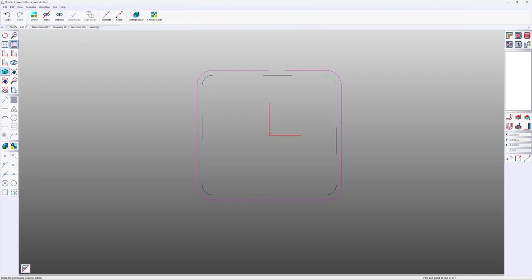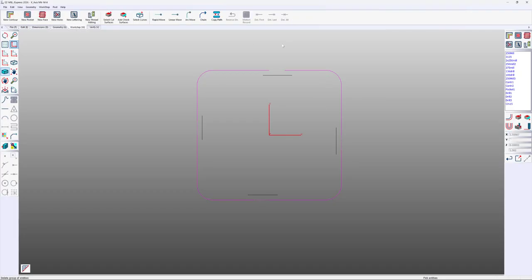Then I'll just go in and delete, just cleaning it up a little bit, get rid of the geometry I don't need. So remember that curve was still active. I didn't delete it, I just cleared the links. So I'm going to go to linear move. Now I want to pick the end and over here so I get exact snapping. So we'll snap to all. There's my line. We're going to wrap it over to this point here.